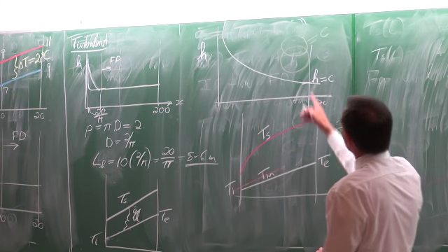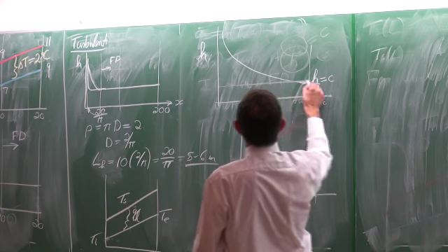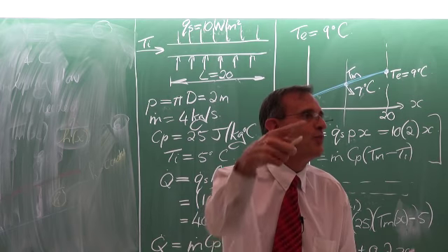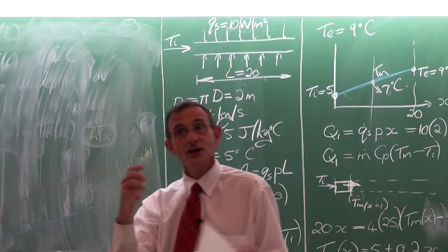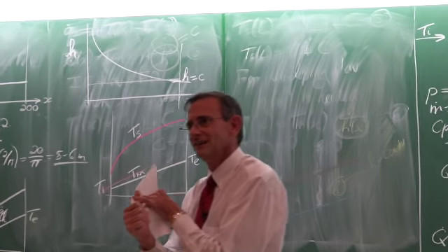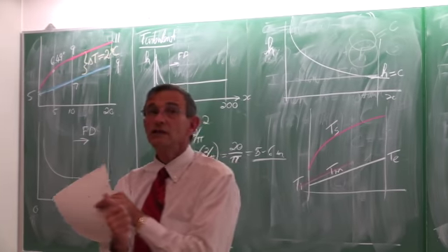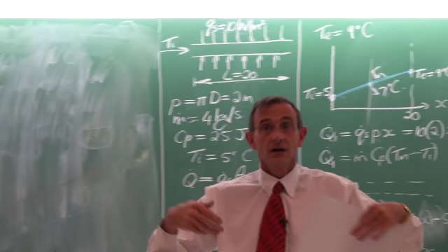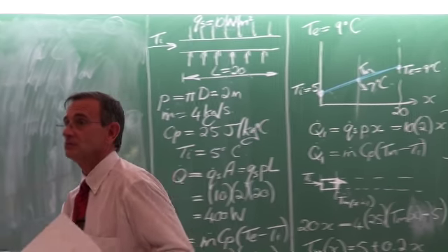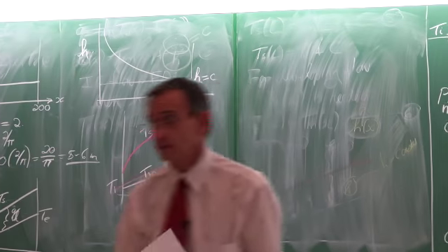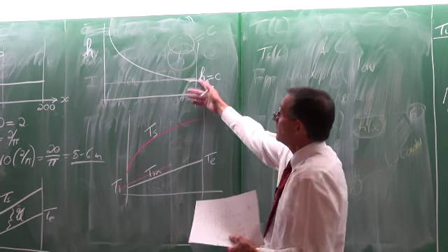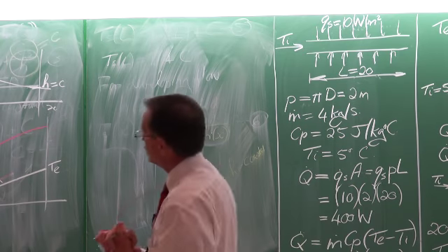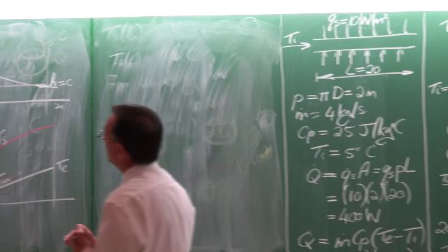So for the heat transfer coefficient, what you actually now do is you say, well, that is the average, I design with it. I know it will be more. And if it is more, I know I can get better heat transfer. And if by time there's erosion or corrosion or stuff on the outside, I can still deliver the heat transfer rate that I should. So my design is a little bit more conservative. So that is why in many cases people will use the fully developed one and actually not take into consideration how the flow is developing.